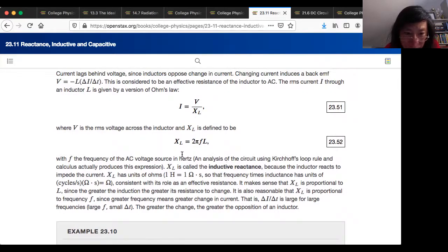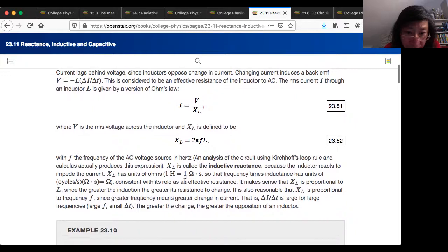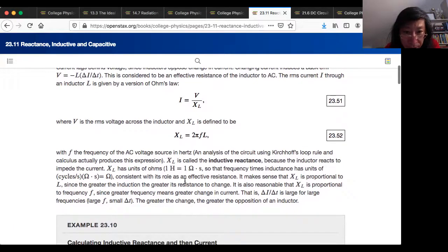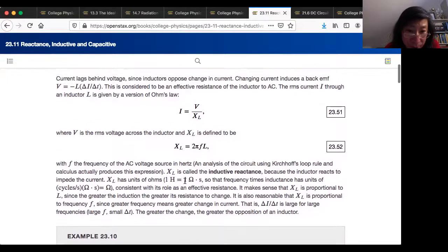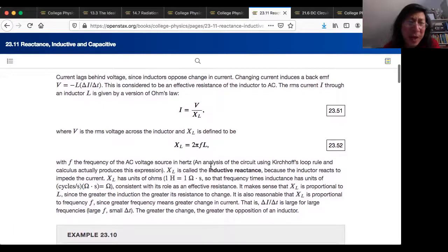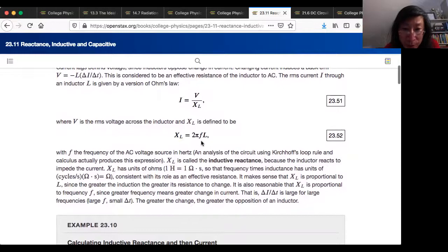So this is the equivalent of the resistance that a conductor produces, but it's called the inductive reactance. Does that make sense? It's in ohms, in the same way that electromotive force is in volts. It's the same kind of unit, and that's the analog between alternating current and direct current circuits. It's kind of interesting. I could derive this with calculus, and you can see how they all fit together in a really beautiful conceptual way.